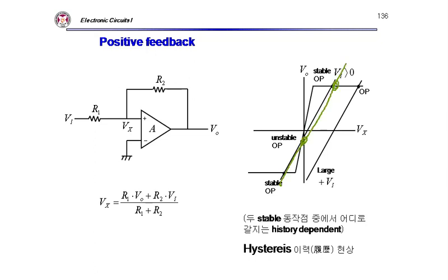So I have 3 operating points here. But if you look at it, this is a very unstable point. If there is some noise in Vx, say Vx increases a little bit, then VO increases much larger, then this larger increase will further increase this one, and finally it explodes. It doesn't stay there, right?